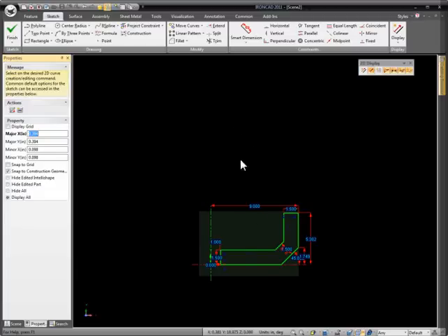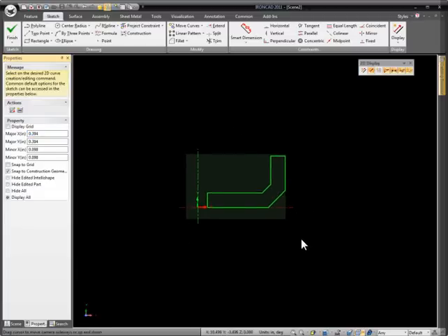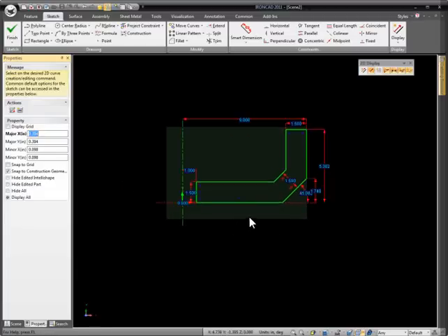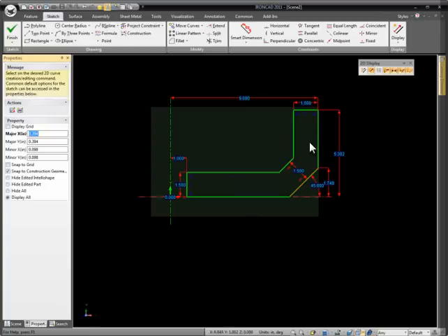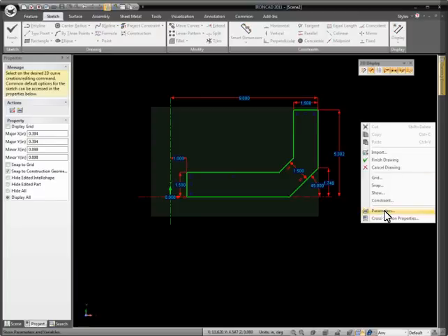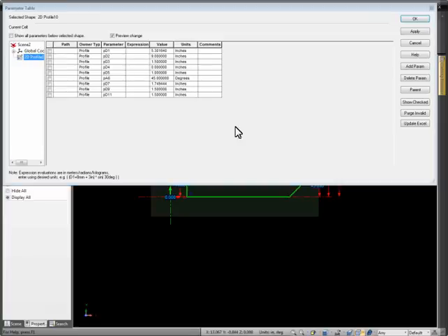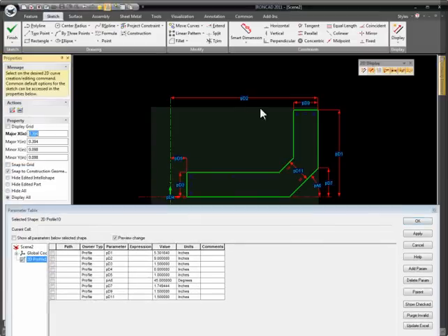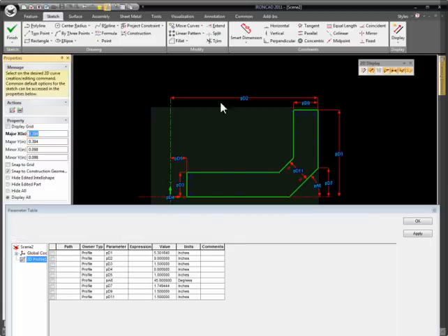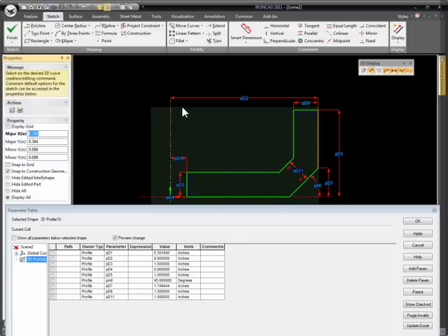And so just be aware when you use those constraints, but they are useful in some operations. Some of the things with these constraints to note, these can be used also in parametric relationships. If you right-click here or at the scene level, you'll have parameters that define all your sketch elements. If you come out here, you'll see these are defining P1, PD1, which dimensions out here is PD1. These are the constraints elements.